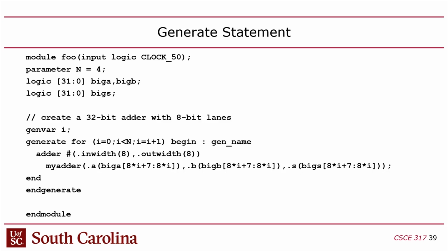So this is useful if you want to create a multi-core CPU, or you want to have something that you can create copies of. Now you might say that looks kind of advanced for just introducing, and it is, but in lab 3, we're going to use this to create one PWM generator for each of the 26 LEDs. That's the reason I'm showing you this. This is where this is going.